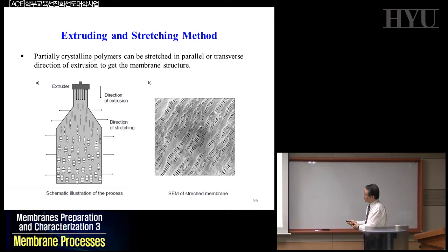It passes through the extruder, and from the gravitational forces you stretch and orient them in the actual direction, but perpendicular to that direction you still have stretching, so that you can have biaxial stretching to induce high porosities. But the rate of stretching between the axial and the perpendicular direction will make your fiber orientation, or the pore orientation, different.